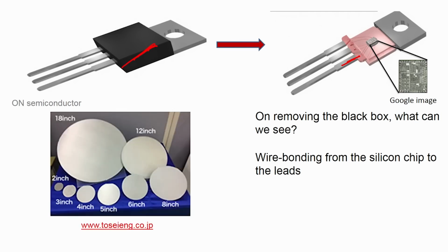Now, if I talk about silicon wafers, what is the size of silicon wafers? Is it 2 inch, 3 inch, or 4 inch? What is the current wafer size that industry is using? Is it 12 inch, is it 18 inch? I think we have discussed that the size of the silicon wafer matters, because by increasing the size you can fabricate more transistors on the same wafer, and thus you can reduce the cost, because your throughput, or the number of chips on the silicon, will increase.